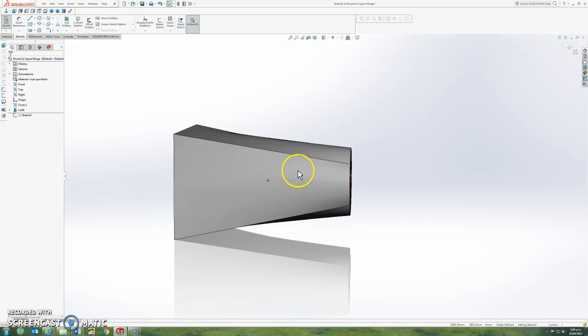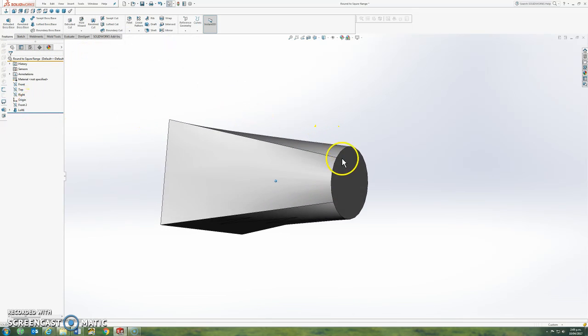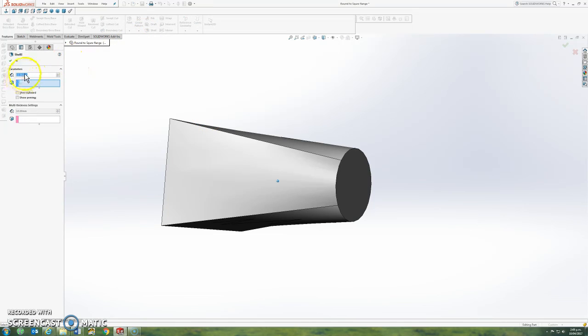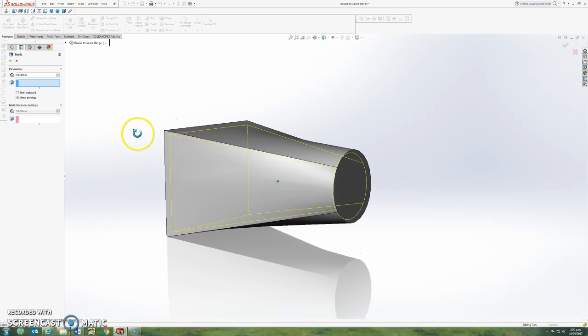Obviously we wanted ours to be a pipe. You're not going to get a lot of material flowing through this. So what I'm going to do is hollow it and make it a shell. So I can exit the sketch. Okay, so I want to leave 10mm of material in this and use that as the central middle bit of my pipe. So I'm going to choose, where are we? Shelling tool, show preview.